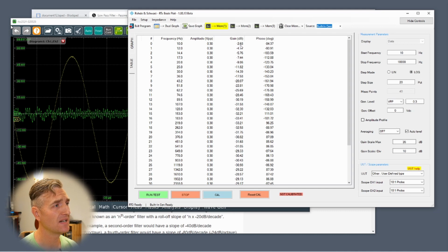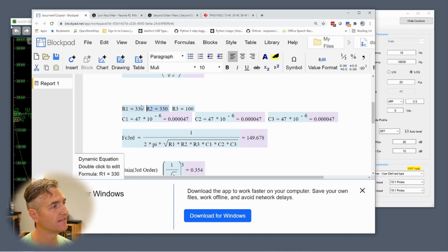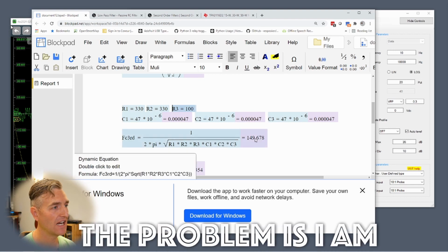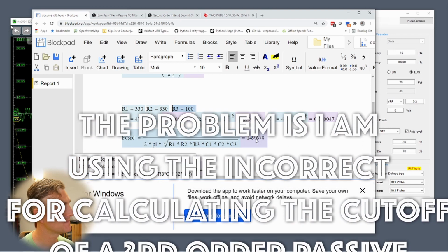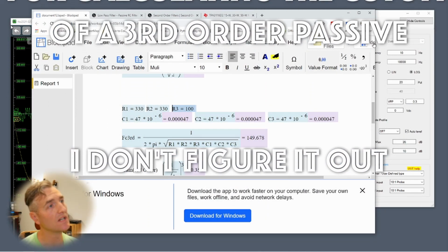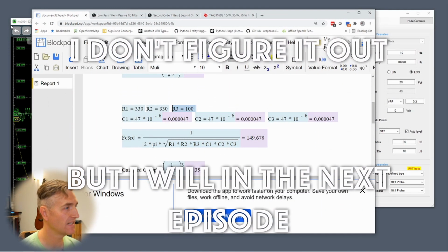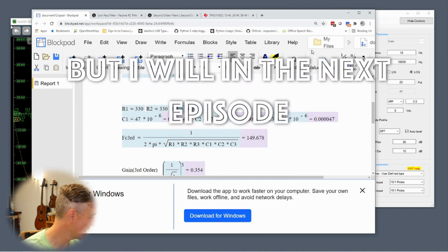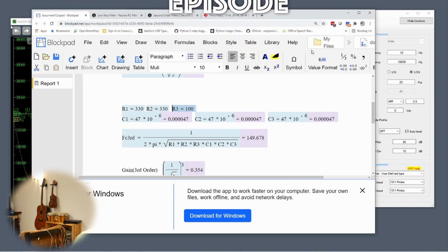So if I started out at -2 and I go to -5, I already feel like I'm on my slope at this point. And 14 hertz. 14 hertz. You know what? If I have all my R's and my C's calculated correctly, I would expect 149 hertz, but I'm getting 14 hertz. I'll tell you what, it feels like I've got a power of 10 missing somewhere.